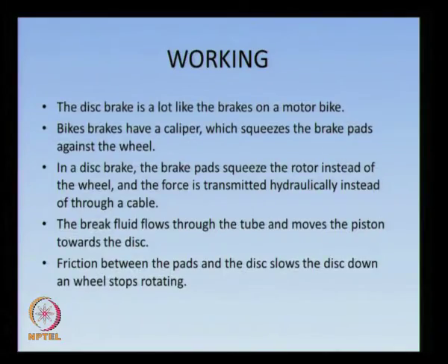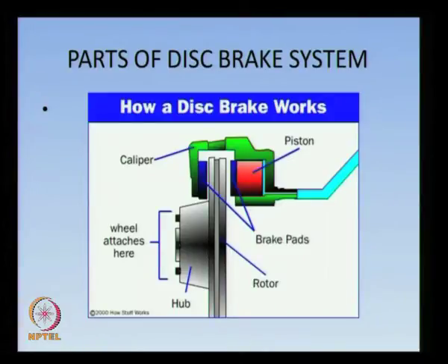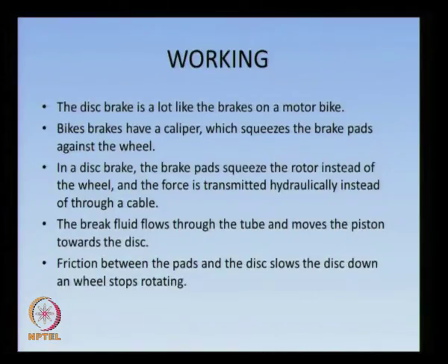Working. A disc brake is a lot like the brakes on a motor vehicle. Brakes have a caliper which squeezes the brake pads against the wheel. In a disc brake, the brake pads squeeze the rotor instead of the wheel, as the force is transmitted hydraulically